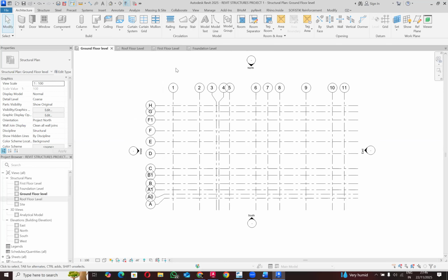You have your grid lines. Now you move on to modeling our structural elements. In order to model your structural element, you have to understand the prerequisites, the sizes of each of these members, and then study the elevation differences in the architectural plan very well to the T. Then you can remodel that precisely how it is in the architectural structural model, right? So you're following that order of design.